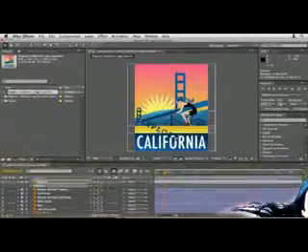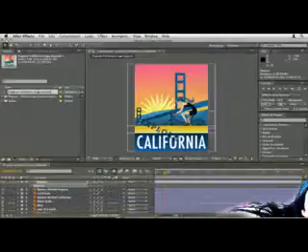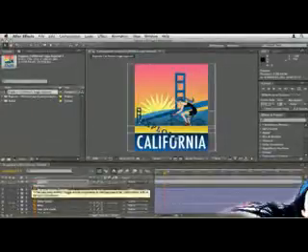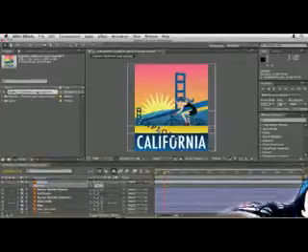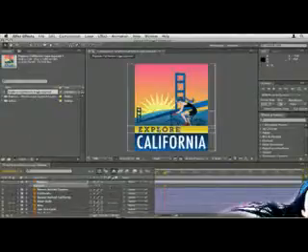But when you animate something, you want it to change value over time. The way that we do that is with the stopwatch. And really, animation is a 3-step process. I'm going to go ahead and click this value, and when we click that value once, we get a field where we can manually type in a value. So I'm going to type in 0 and press enter.